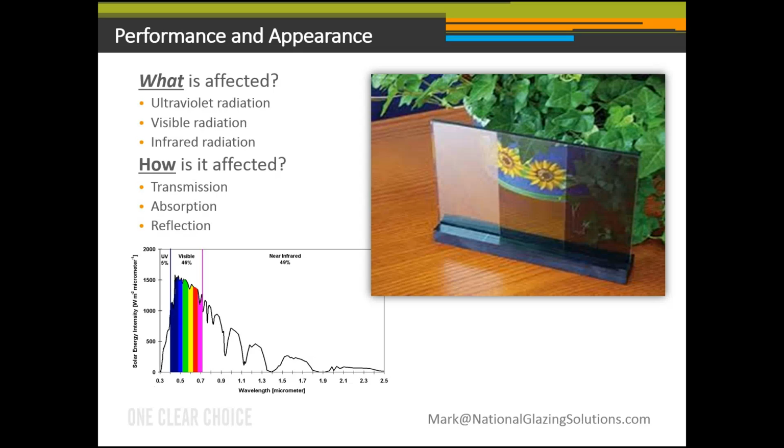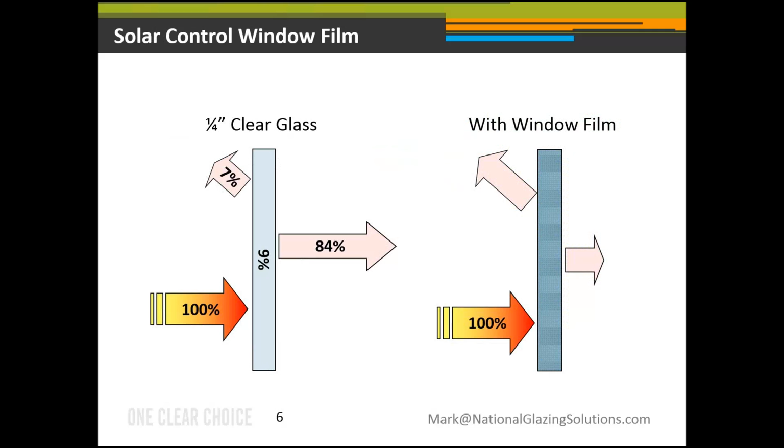The film in the middle has changed infrared, like the one on the left, by increasing infrared reflection, but it does not have visible reflection. And the film on the right has changed by decreasing the visible light transmission. It looks a little darker, but it has really not changed visible light reflection much. And these are only three examples to illustrate how we need to be careful not to necessarily associate performance and appearance. Let's get the film to do what we want it to do and then look the way we want it to look. This next slide goes on a little deeper to that reflective film sample on the left.